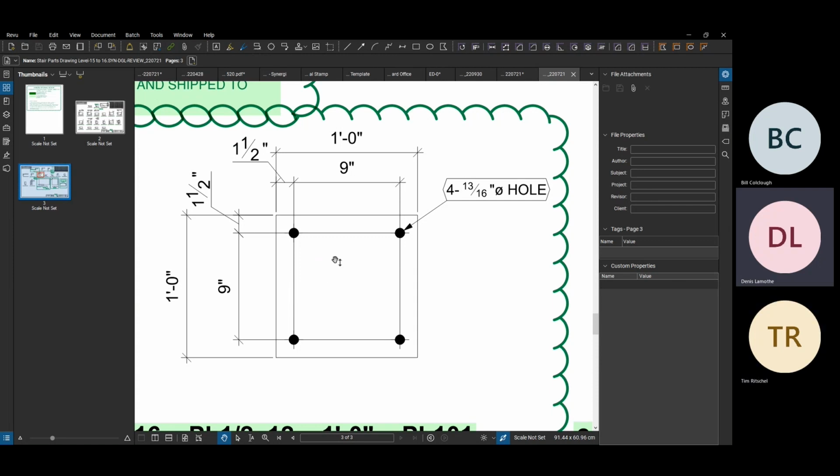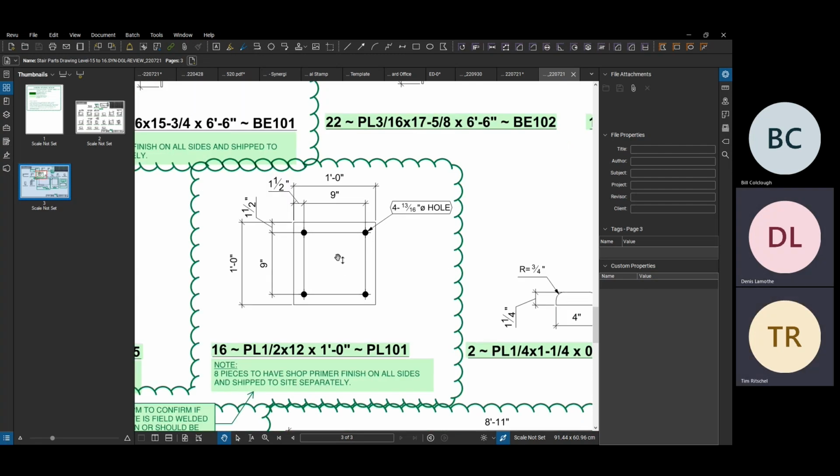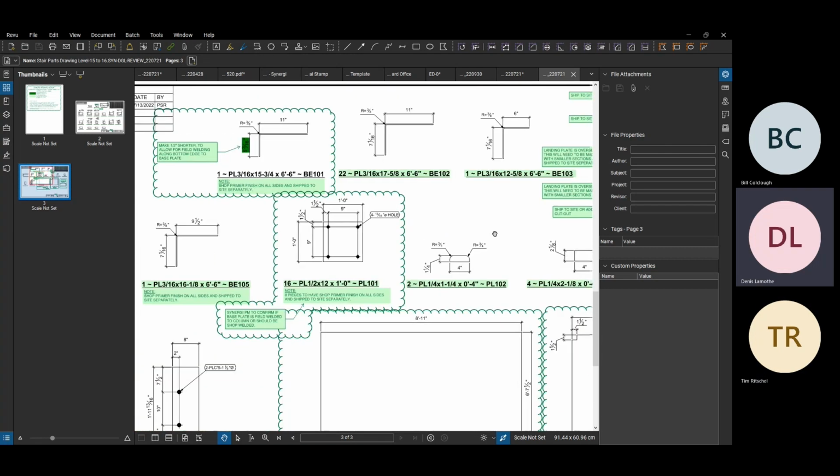On the part, they'll take the plate and measure the center. They'll make a punch, and then they could just use a press drill or whatever other tool they use to drill out the hole and then thread it if it's needed. So dimension center of holes, overall dimensions, angles. I mean, dimensioning is fairly straightforward.